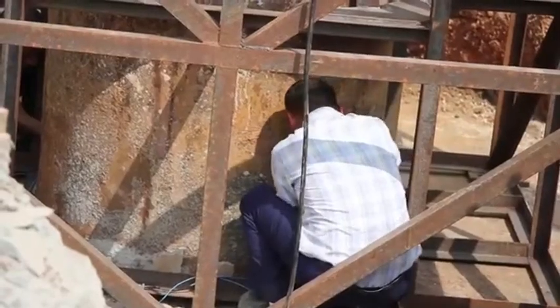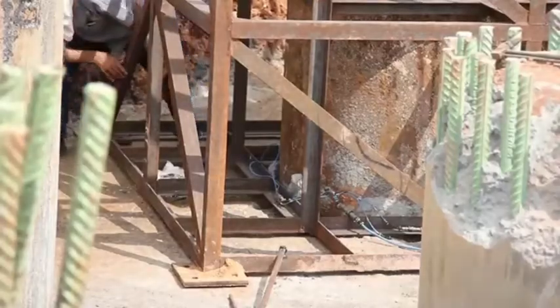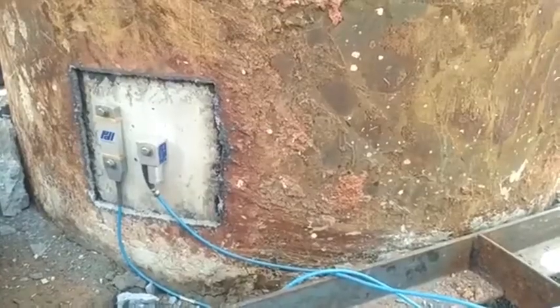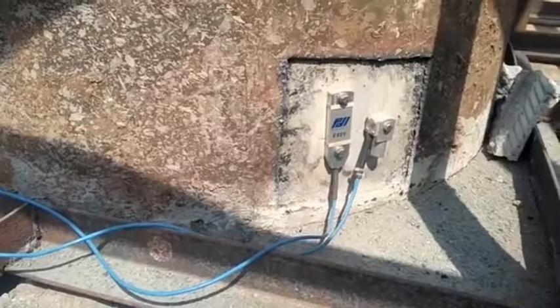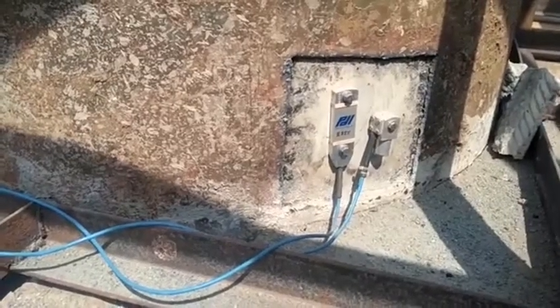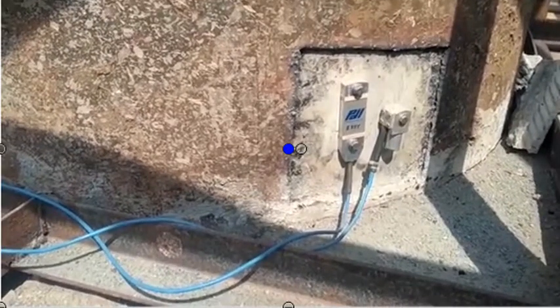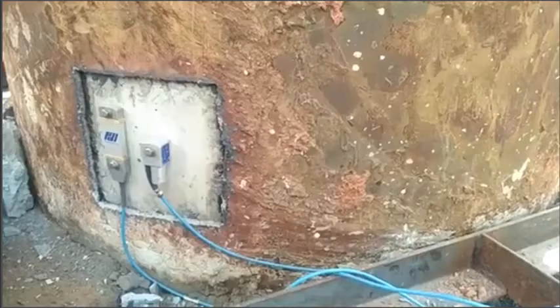When you want to carry out a dynamic pile load test, 2 pairs of sensors are attached to 2 opposite sides of the pile. One sensor is a strain transducer and the other is an accelerometer. That is, one strain transducer and one accelerometer will be placed at one side of the pile. Another strain transducer and one more accelerometer will be placed at the other side of the pile, making 4 sensors. So 2 pairs of sensors.